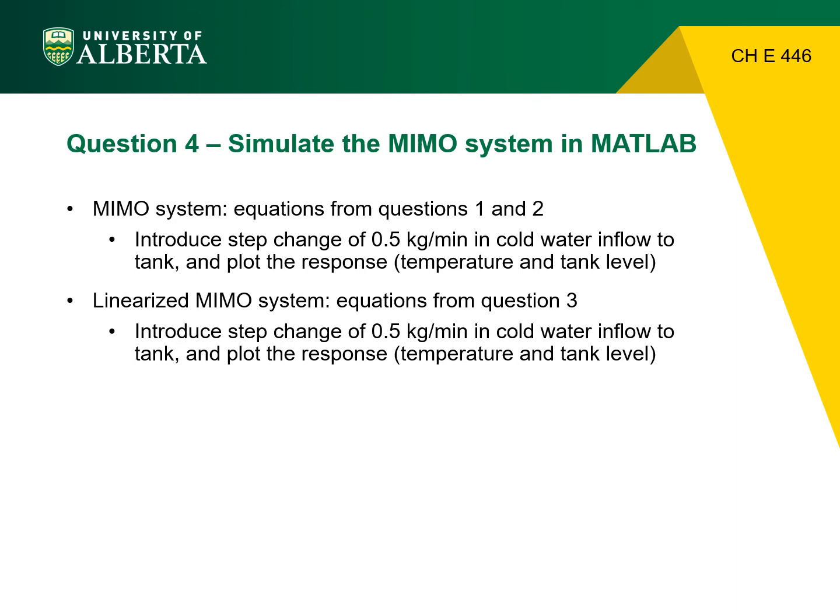For both simulations, you are asked to plot the response of the system when there is a step change of 0.5 kg per minute in the cold water inflow to the tank from its steady state value. Finally, you are asked to compare and analyze the responses resulting from both simulations. In order to solve question 4, of course, the main thing you need to know is how to simulate a system of ODEs in MATLAB.